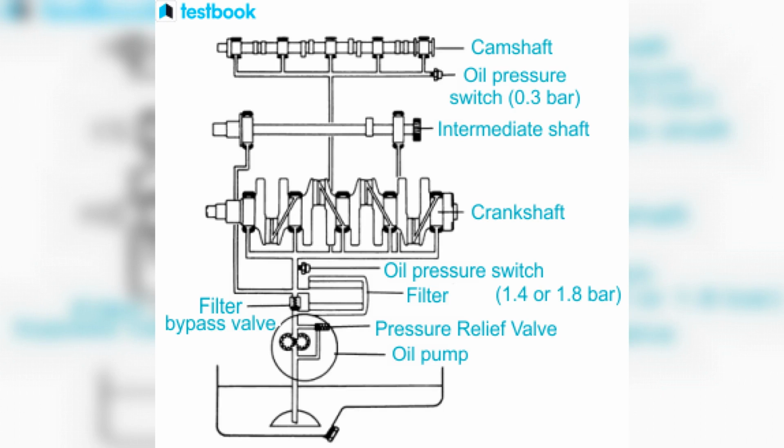and then it's the turn of the upper connecting rod supports to the piston group pins. The next stage of the path is cylinder lubrication, where the fluid enters through nozzles or special holes located in the lower connecting rod support. All other components of the power unit are lubricated by spraying. The way it works is as follows. By flowing out through the gaps in the above-described lubricated surfaces, the oil is splashed onto the moving parts of the timing gear and crank mechanism.